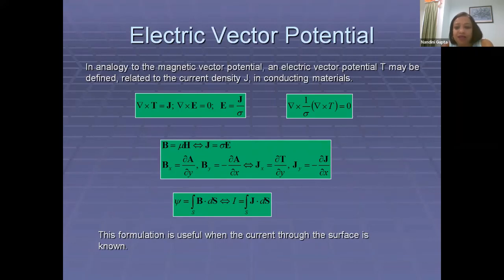And to round off, since we have been talking about scalar and vector potentials, and we have shown an analogy between the electrostatic fields and the magnetostatic fields. Now, in the electrostatic field, we have phi as a scalar potential. Here, we also have the magnetic scalar potential Vm, which holds when you have J not equal to 0.